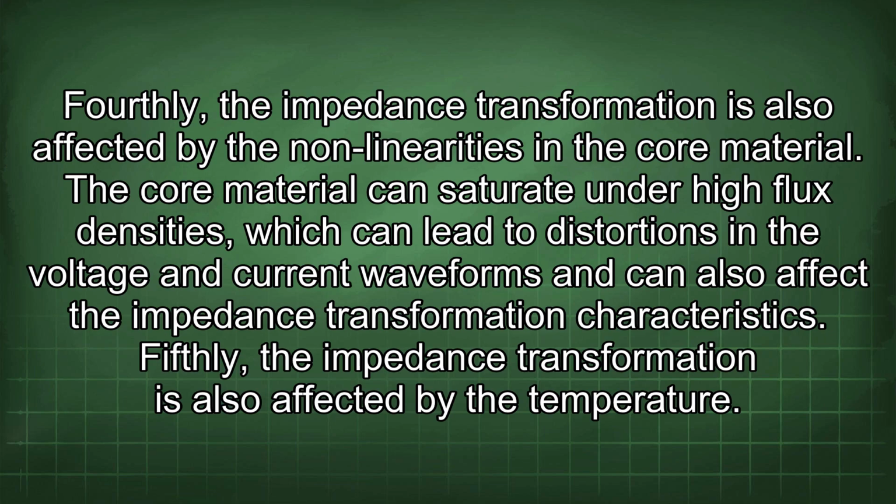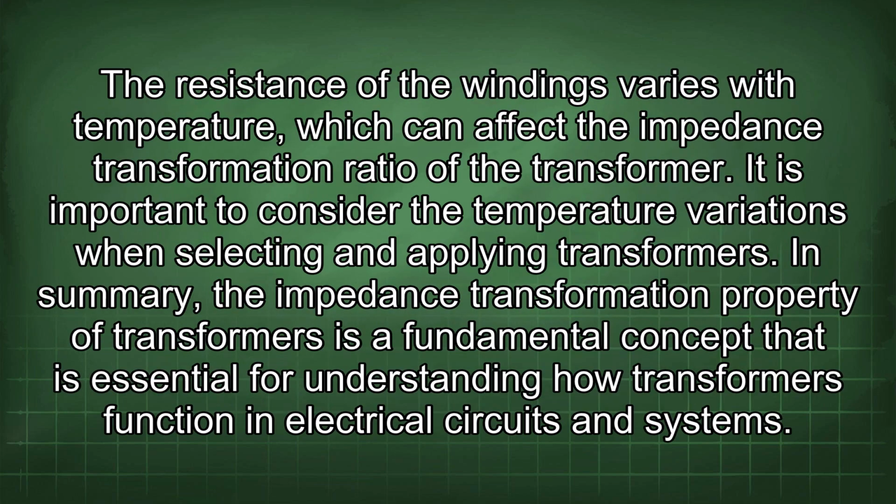Fifthly, the impedance transformation is also affected by the temperature. The resistance of the windings varies with temperature, which can affect the impedance transformation ratio of the transformer. It is important to consider the temperature variations when selecting and applying transformers. In summary, the impedance transformation property of transformers is a fundamental concept that is essential for understanding how transformers function in electrical circuits and systems.